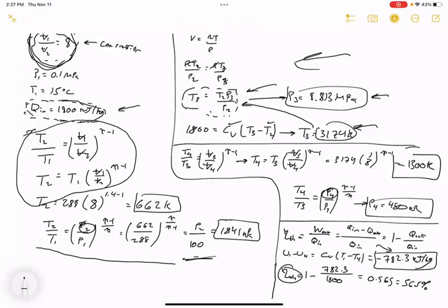And then you're going to use your knowledge of the state, maybe at state 1, combined with any combination of ideal gas law, property tables, knowing what type of process it is and what's held constant throughout that process. You're going to use all that information to find the states everywhere else. And then by knowing the states, you know things about the internal energy or the enthalpy, and you can use that to find the amount of work output, the amount of heat input, the amount of heat output, as in heat rejection. So this is sort of what you want to be able to do.